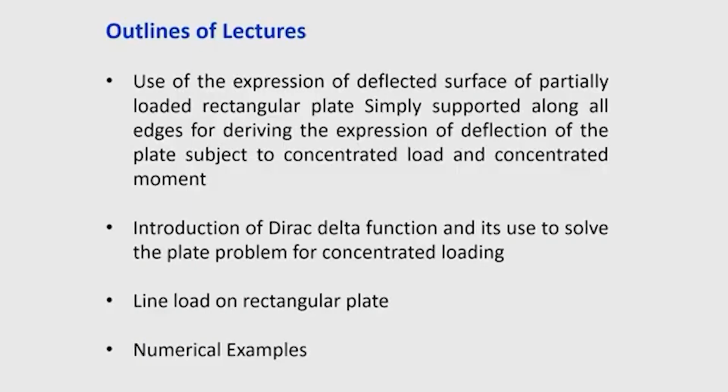Concentrated load is very common in bridges actually. When a bridge deck, which can be modeled as a plate, has vehicle wheels moving on it, the wheel loads are transferred to the bridge deck as concentrated loads. So, the concentrated load formulation we want to show today. If you refer to the reinforced concrete design code, you will find that the effective width method is given for concentrated load, but here we will derive the exact expression with the help of plate theory. Okay. So, this is our first objective in the lecture.